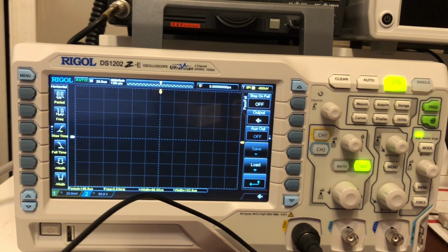Okay, first up is math operations: algebra operations, spectrum operation, FFT, logic operations, function operations, and filter: low pass, high pass, band stop. Included in function operations are integer, difference, square root, log, linear, exponential, and ABS. Fixed operation is a combination of two operations. For details, please refer to the introduction in FX operation.